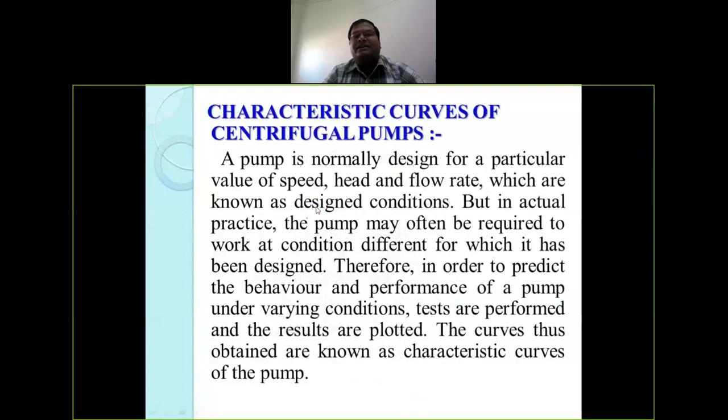Now the next subtopic is characteristic curves of a centrifugal pump. Okay, so what is the meaning of that? A pump is normally designed for a particular value of speed, head and flow rate, which are known as the design condition.